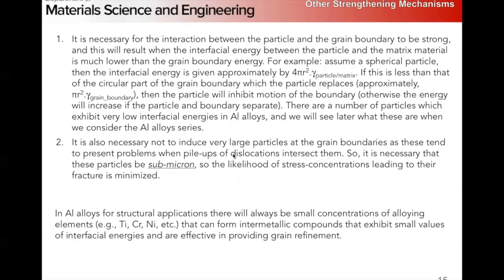Okay, so we can pin those grain boundaries by considering particles, right? If we have a very fine dispersion of particles, so how can we do that, right? The first thing we need to consider is that we want the interfacial energy of the particle matrix to be very low, right? In fact, we want it to be much lower than the grain boundary energy,